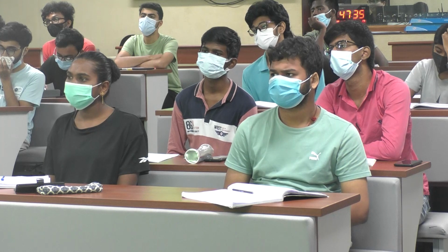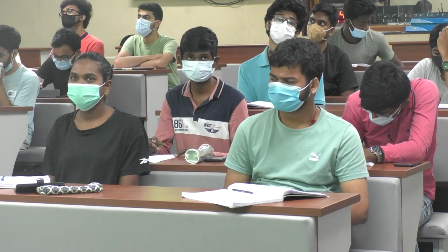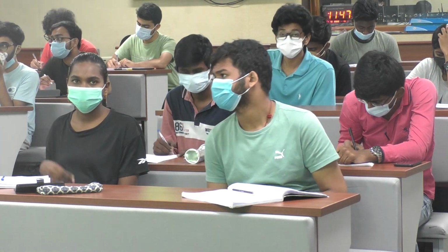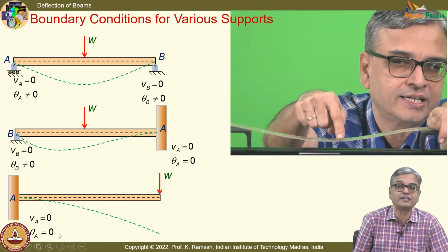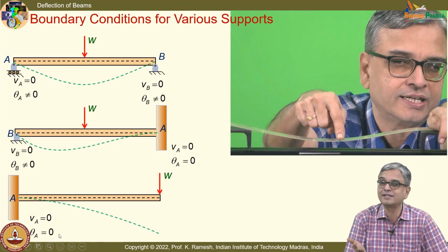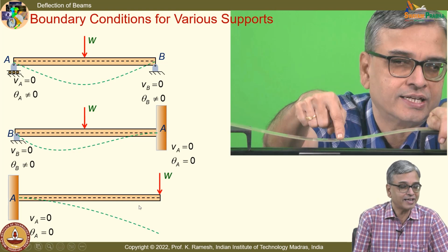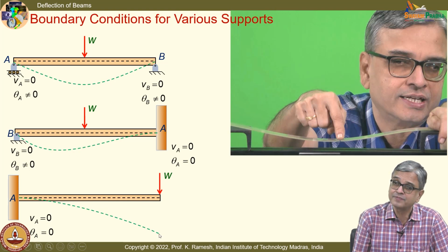If you recognize, your job of handling deflection is extremely simple. Fine. And now, I can also have the conditions. I can only write VA equal to 0 and theta A equal to 0. I can't say anything beyond that. On the free end, okay, it can have slope as well as deflection.